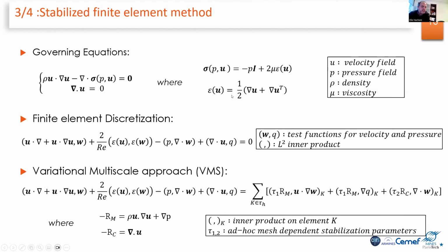The third ingredient is about how to solve the finite element solver, the solver itself. Even if it's a flow solver, or even Darcy, you need to take care in finite element how to solve in a P1 resolution, for example, P1 for the velocity, P1 for the pressure. There is a way of doing it using a variational multi-scale approach, which is very nice.